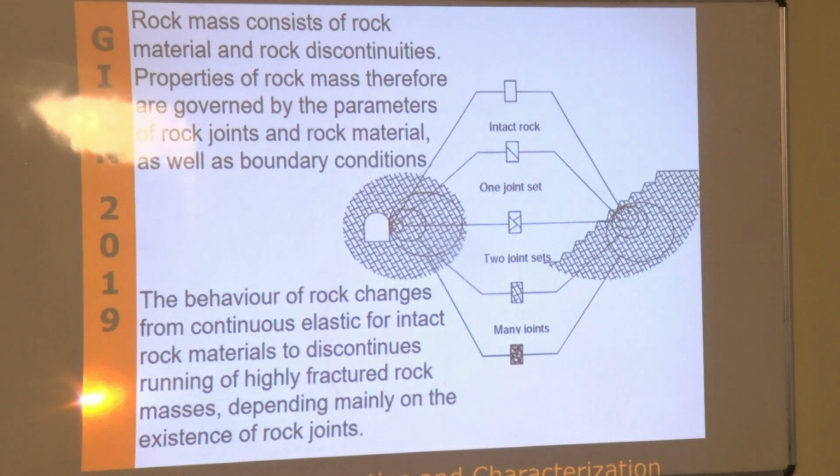Even in the test I showed you this morning, there was that plane that screwed up our calculations and gave us a very low strength value. But that was not just an unlucky sample. It's the standard type of feature that is always present in your rock mass.